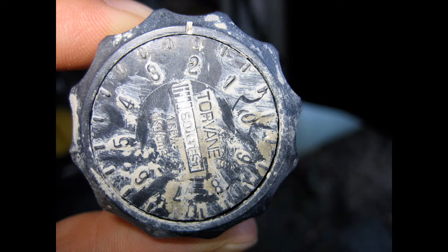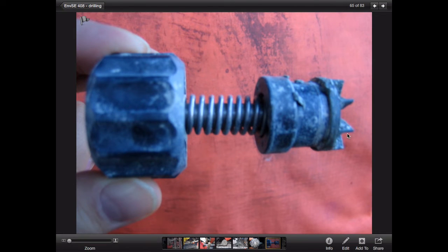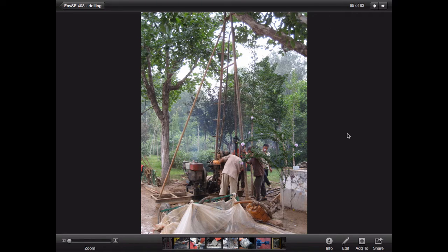Measuring the strength at the end. The Torvane is just, you twist it, it's like a torque wrench with some little feet in it that go into the clay sample. When you twist it with enough torque, those feet will fail and turn, and you know that you've failed it. So quite rudimentary, but it does a job.